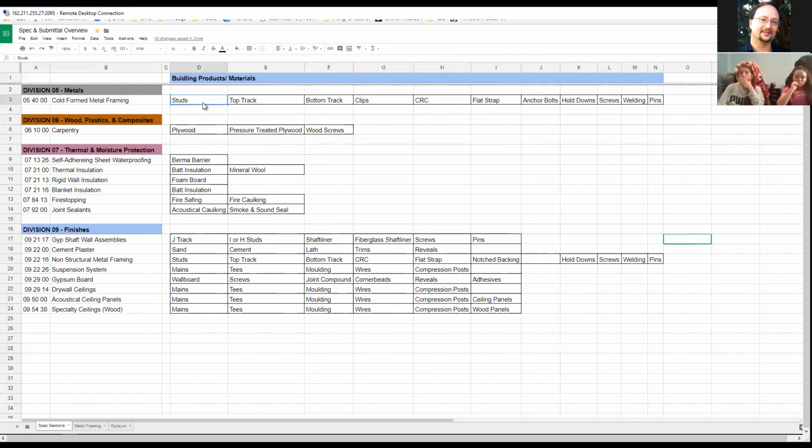Like a 22 round, they will refer to it as a 22 load. You have 22 loads, you have 12 gauge loads. The bigger the number, the larger the capacity of gunpowder that's used to push the pin into the steel. And it sounds like a shotgun shot. So this is where safety, they'll put in ear protection, things like that.